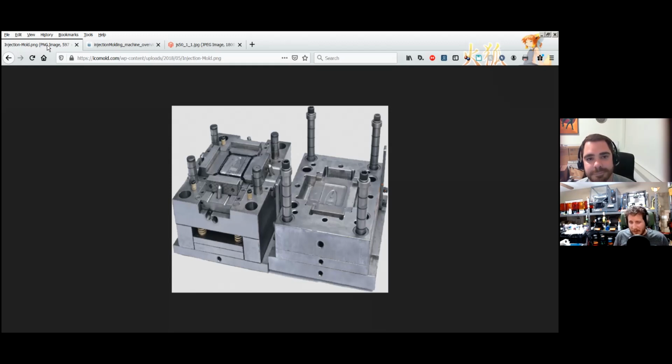Delrin is a self-lubricating plastic, which makes it phenomenal for these types of feeders. But it's also quite brittle. It doesn't flex a lot before it breaks. And when you're basically buzzing the crap out of it, you're going to have problems. So this customer understands the use case of something like this. And don't get me wrong, I would love nothing more than to have 15 machines doing $2,000 parts that we can do every single week. But it's not realistic for where we're at right now as a company. We do a lot of small stuff.